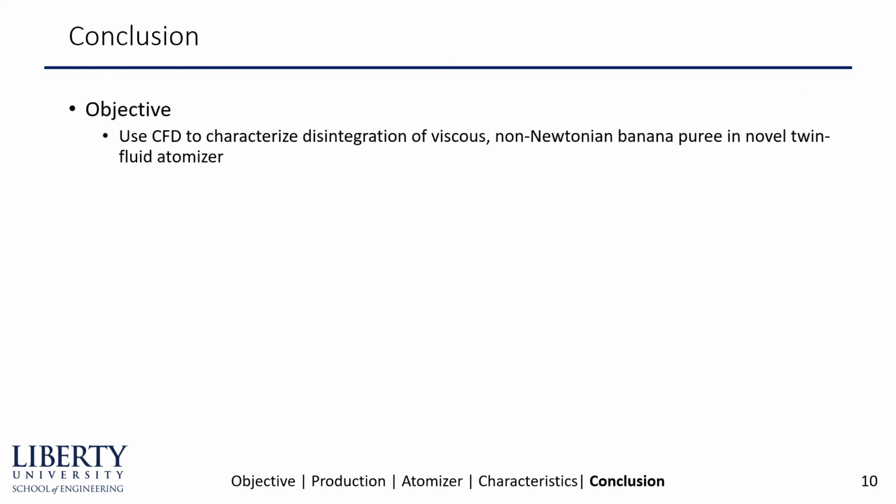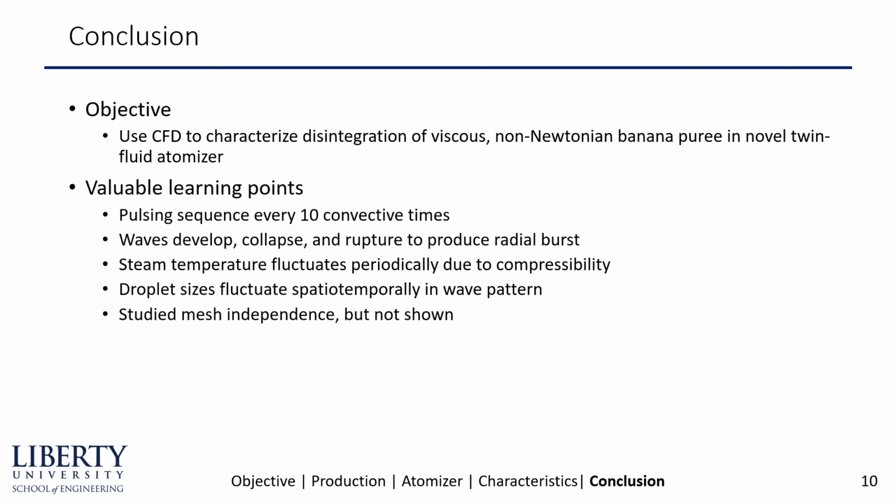In conclusion, our objective was to use CFD to characterize the disintegration of viscous, non-Newtonian banana puree in a novel twin fluid atomizer. Some of the valuable learning points from our research are that the pulsing sequence occurs every 10 convective times, and we see waves develop, collapse, and rupture to produce radial bursting periodically.